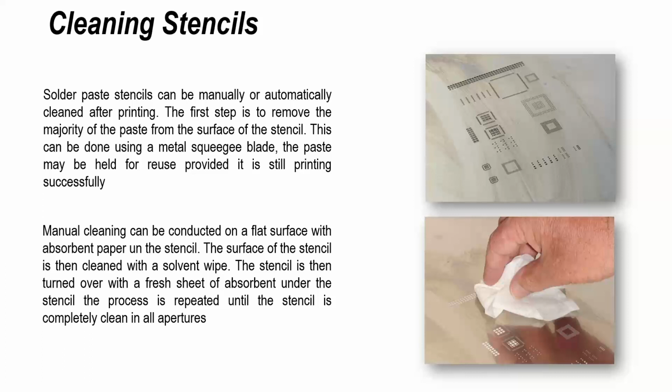So whatever procedure you use, you've got to guarantee that it's giving you a clean stencil. There's no residues on the surface, both top and bottom, and all the apertures are perfectly clean. You must make sure that you select the right cleaning chemistry, but that's down to you because you know what paste you're using, what machine you're going to be using. So whatever technique you use, you've got to assess the materials based on that type of technology.